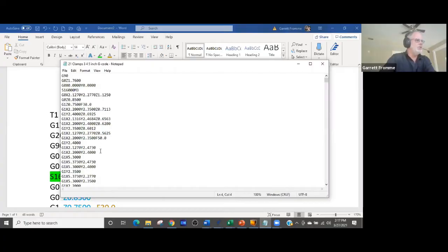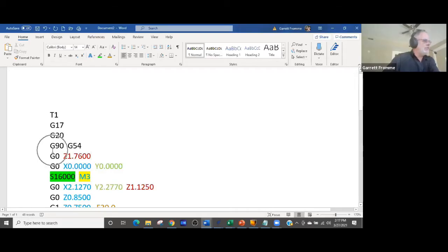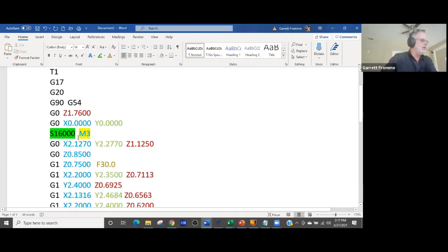When you're looking at a G code file here, you don't just have G's in the front of lines. You also have a T, there will be an S, we have an M, we have an F. So there's lots of different codes that are actually punched out from your post processor to create this G code file. Now I'm going to step back a little bit. I explained post processors before. Post processors are programs that convert the binary into this type of format.